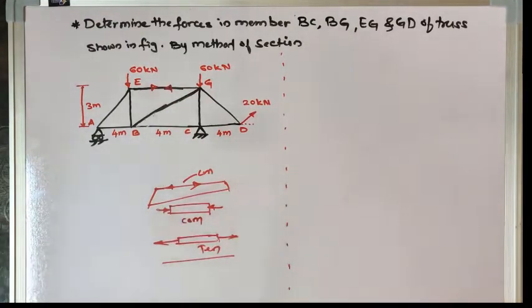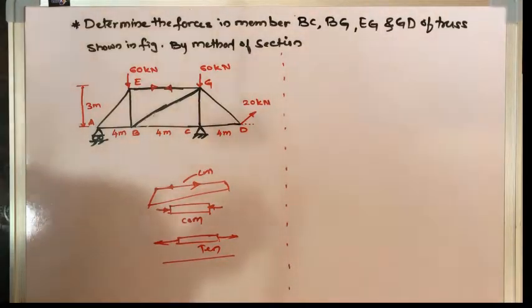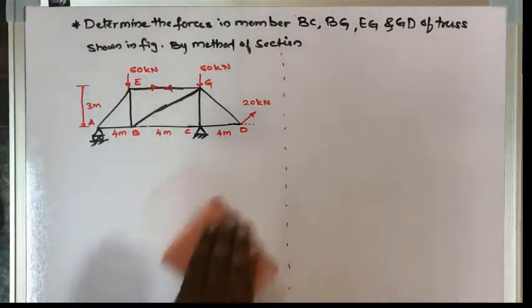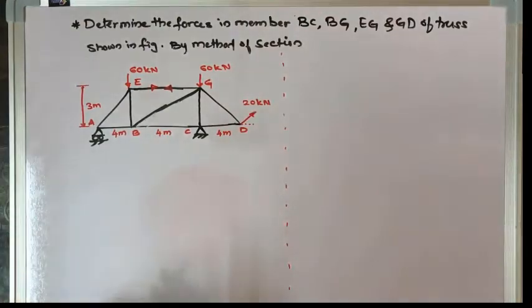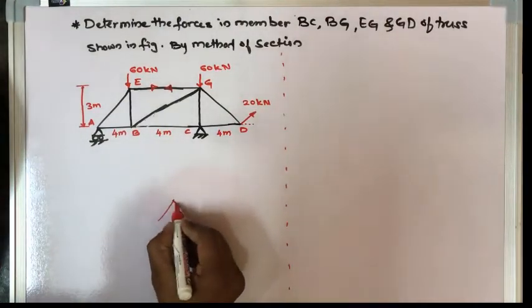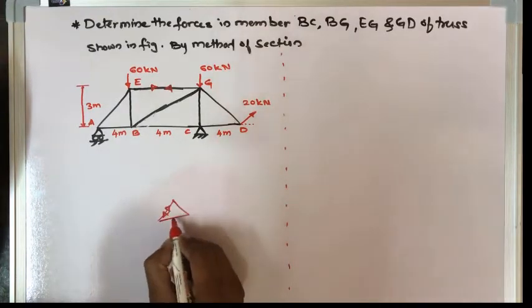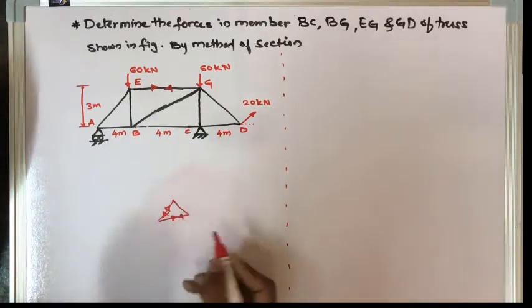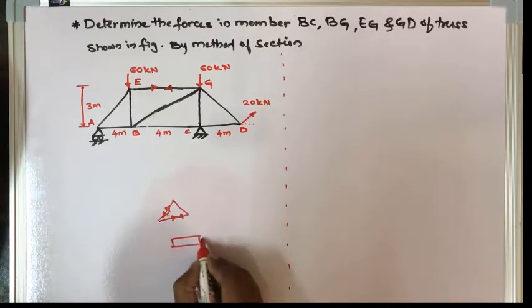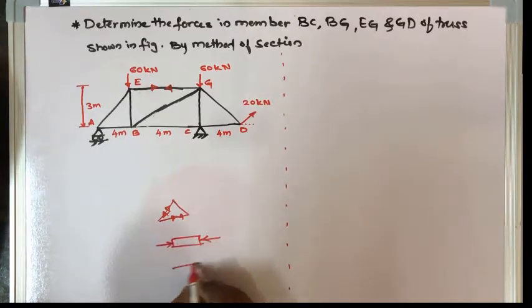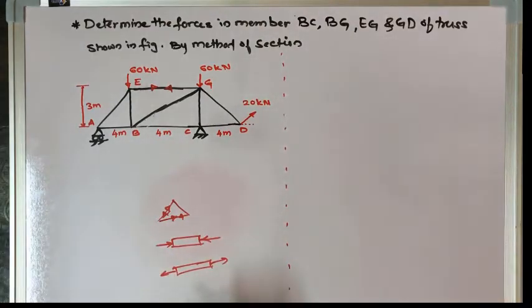It's the reverse way. So in a truss, a compression member is nothing but an outward force, and a tension member is nothing but an inward force. But externally, it's the reverse. Inward force is compression, outward force is tension, correct? So this is the concept behind this.